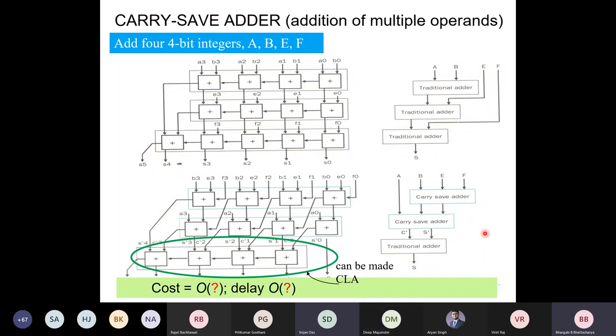The prefix sum. Not prefix, but just imagine that. What is it? Just a simple binary tree. It's not binary because it has three inputs, right? So yes, we will be constructing a tree. This is a serial chain. So we will transform the chain to a tree. But this tree has three inputs, as you can see. A slightly different type of tree. Yes, you are right. Because it is serial, the depth increases, and that gives you this diagonal delay here.